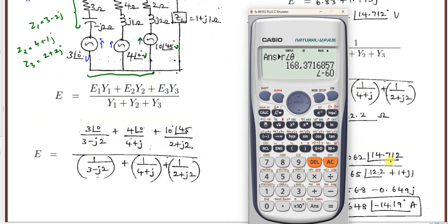So I will do this calculation. Please all of you verify. First, I'll repeat once again. First go to mode. In the mode, select complex, which is number 2. If it is in complex mode, it will show CMPLX, and this should be D. D means degree. Sometimes R will be radians. Then go to setup and change it to degree by default.